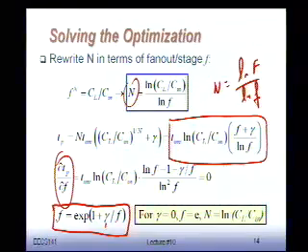And for the number of stages, since ln f is 1, this factor becomes equal to 0. If f is equal to e, this is equal to 1, and n is nothing else than the natural logarithm of my large fan-out factor F. That's what is written here. So out of there, we have the number of stages.